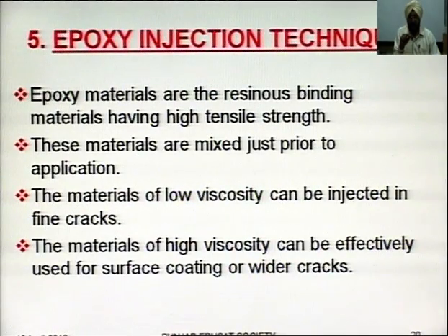In the case of fine cracks, low viscosity epoxies flow in easily as compared to the high viscosity epoxies. Materials of high viscosities can be effectively used for surface coatings or wider cracks. So if the cracks are very much wider, epoxy material with high viscosity can be applied. But in the case of fine cracks, the epoxy material has to be of low viscosity. So this is also one of the techniques, called the epoxy injection technique, which can be applied for retrofitting concrete structures.